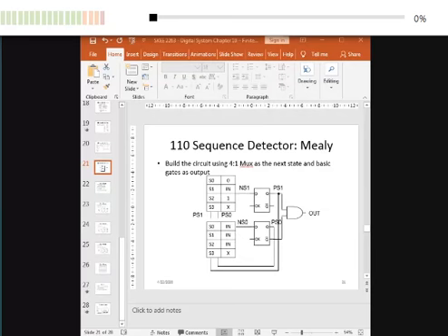That's why you have to write a proposal. You have to plan a block diagram to show how your data path unit should be, how your control unit should be, especially the data path unit. What are the components that you are going to use? Because especially register, you are going to use a lot, isn't it? Because when you want to display on 7 segment, you have to store the data in a register first.